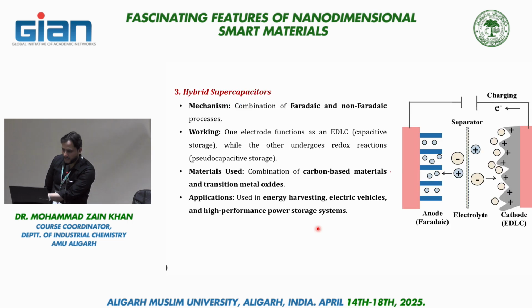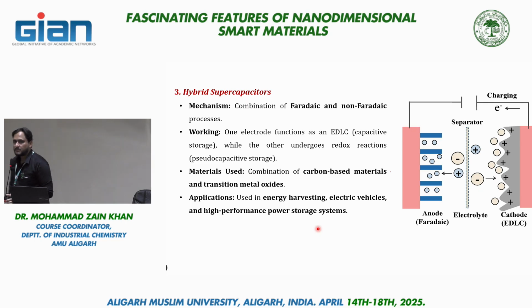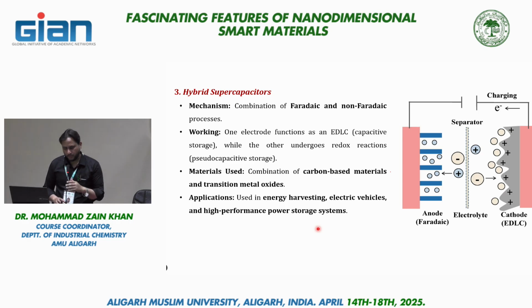This is the model of a hybrid supercapacitor. Do you know the difference between a Faradaic and a non-Faradaic process? Faradaic processes are those where electricity is generated by a Faradaic reaction. Faradaic reaction means when electricity is generated by a redox process, it is called a Faradaic process. And when energy is not generated by a redox process but by some other means, for example, you have given energy from outside, it is called a non-Faradaic process.